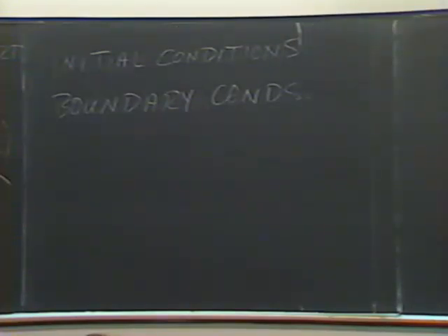The Waterways Experiment Station has successfully used physical models to get U and V. Recall when we walked around the physical model a couple of weeks ago, I pointed out that the physical model is truly a three-dimensional representation of the system. It doesn't have wind effects, but as far as the tidal effects are concerned, it gives a good three-dimensional representation. So you can measure U and V at a number of points in the physical model and use it in this relation. The difficulty is that the physical model is small, so you can't measure at points very close together very well.